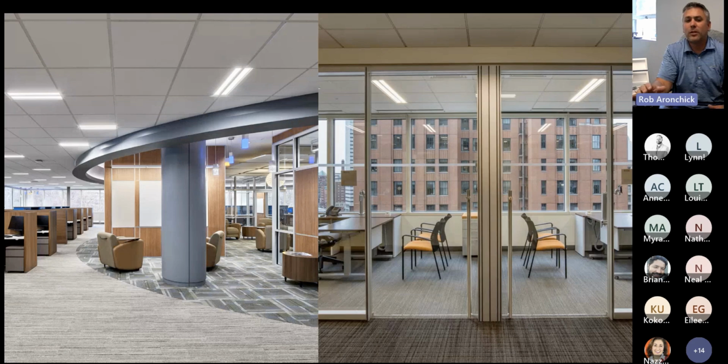Corporate office spaces. We do a lot of corporate interior fit outs. The fixture makes for, again, just a really nice alternative to some other products that maybe you've used for these type of spaces. On the right-hand side, this shows a 4-footer in a 2x2 grid. So regardless of the length of the fixture that you'd like to specify, that can go into any grid dimension. And as I mentioned in the beginning, the T members come up and rest on the flange of the fixture, and then we have accessory clips that will essentially lock in the T-bar to the flange of the fixture so it's not floating around there.